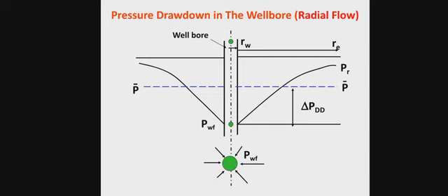Always keep this image in your head, because we are going to make use of it in all the calculations, the Darcy equations, and everything. Keep in mind that the wellbore pressure is always lower than the average reservoir pressure, and in a naturally flowing well, the driving force is the drop in pressure.